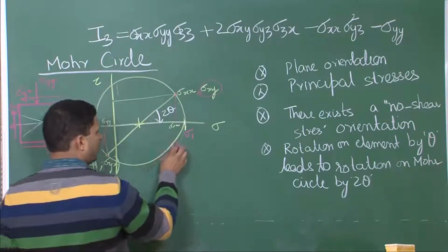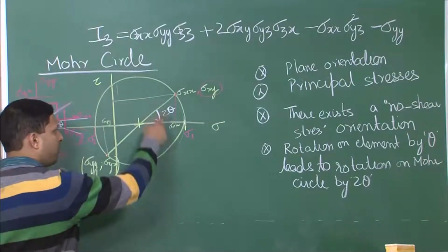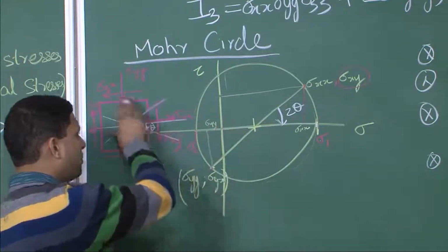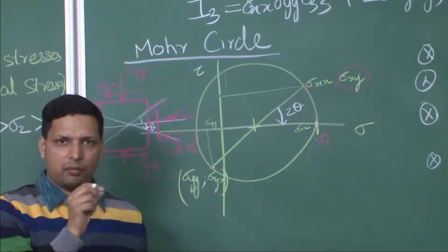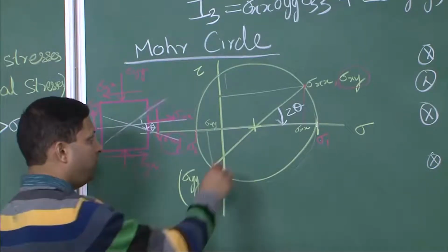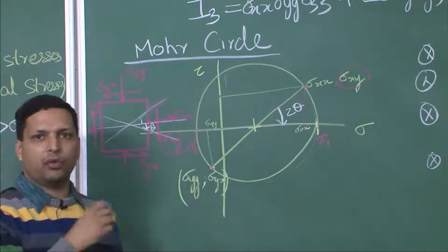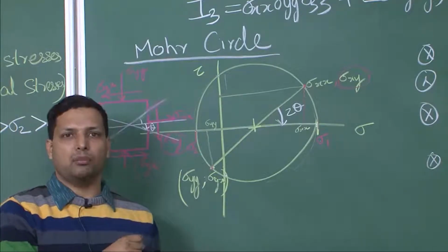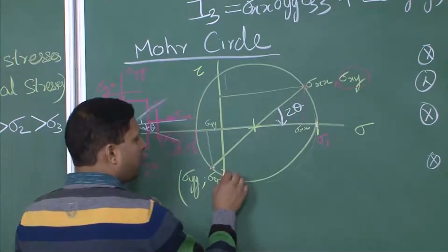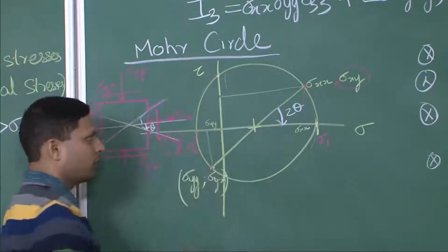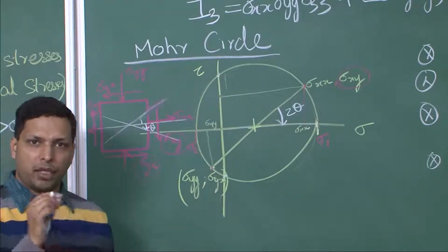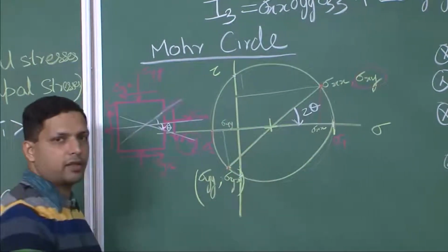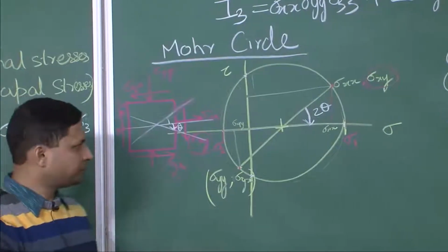If we are talking about this same element, remember this one circle represents one element. Here we can rotate it, and it means we are rotating the same element, or the same point inside the component. But if we draw a new circle over here, it would represent a new or different element on the component. So, we cannot take these 2 points for this same element, but there may of course exist some elements where this and this will be your stresses, sigma xx and sigma yy.